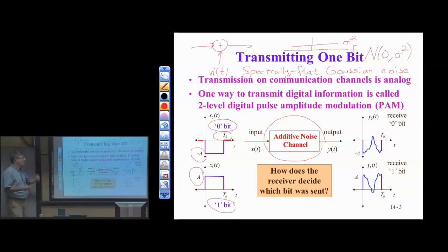Then the power spectrum is this perfectly flat entity in the frequency domain. This is the power spectrum, the power at each frequency location, in magnitudes, absolute value. What this tells us is that the noise is equally present at all frequencies, in theory. And it's a model, so in practice, it's going to vary from this. We'll look at some cases a little bit later.